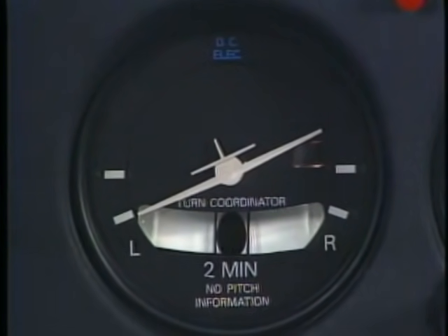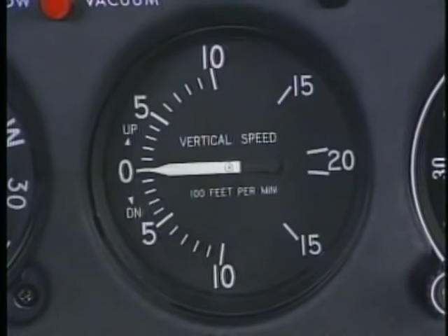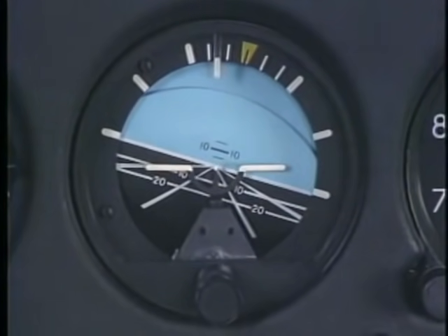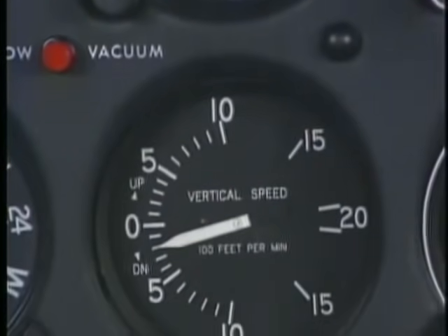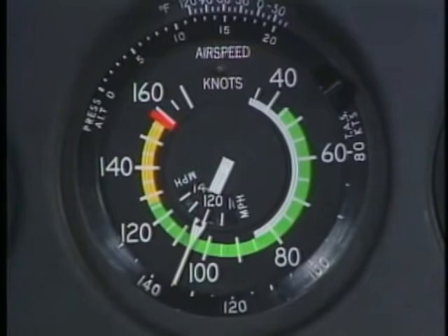No matter what the airspeed, if the wing on the instrument is aligned with the mark and the ball is centered, you're in a standard rate turn. When established in the turn, the altimeter and VSI confirm your pitch attitude. If you observe a deviation, adjust the pitch on the attitude indicator and check the altimeter and VSI to see that you have made the proper correction. The airspeed indicator will directly indicate the need for a power change.